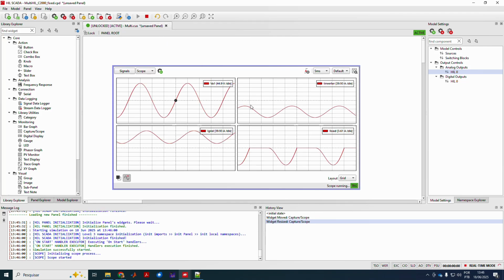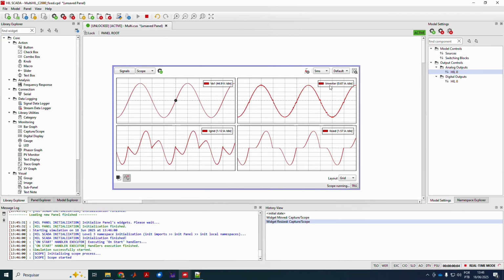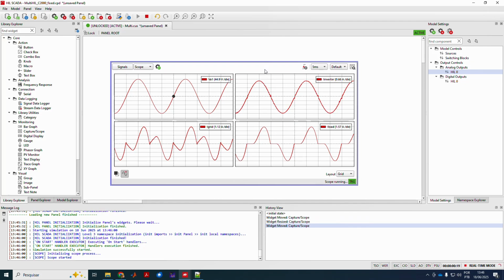If I run, for now I have here the grid voltage, inverter current. Actually it started working correctly right now. The load current and the grid current. In this case I'm just injecting an amount of power into the grid with sinusoidal current, but I can see with this result that the code the software has just generated is actually working. Let's check that in the scope.